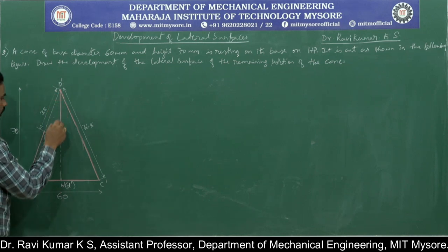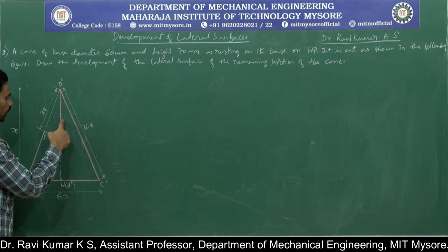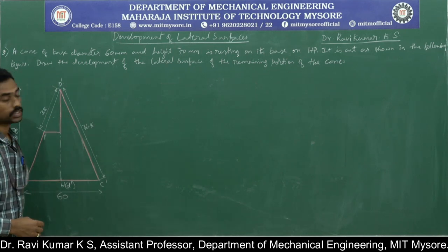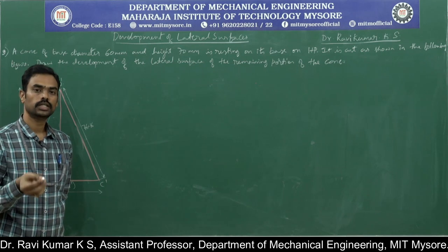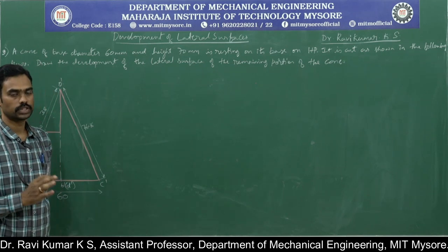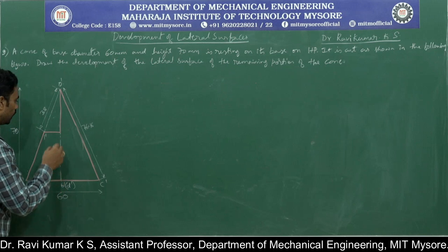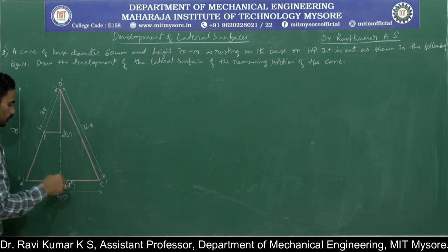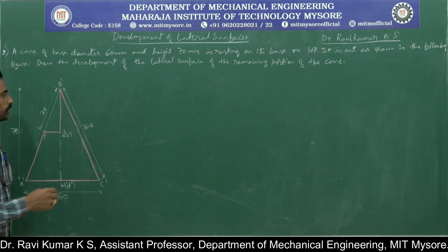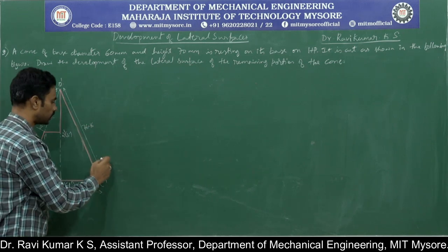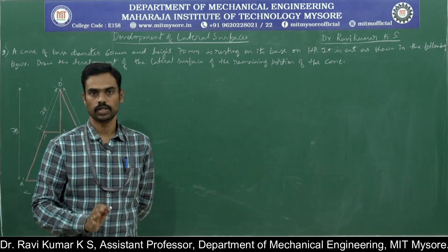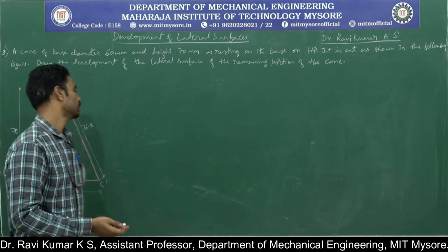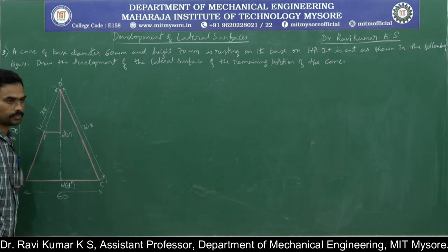Similarly, the cutting plane is cutting the edge O dash B dash or O dash D dash. It is the edge which is appearing, that's it. It is just a constructional edge. So this is 2 dash, again 3 dash in bracket, which is for D. The generator O dash C dash remains unchanged because the section plane is not going to do any damage to the generator O dash C dash.